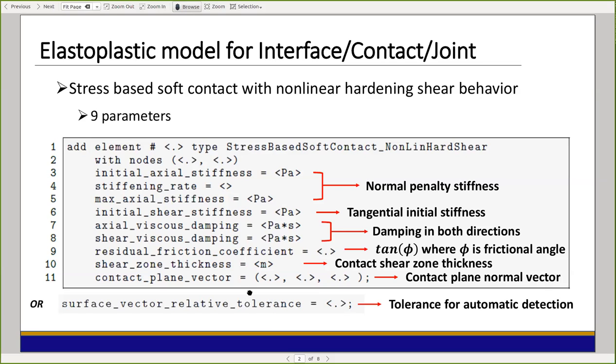Just a comment. This damping that you mentioned is viscous damping. If you think about an interface where something is going to open a gap and close the gap, there will be some suction, some pumping of fluid, in this case air or water. This is the meaning of it in the normal direction. In the shear direction, it's really less than that. But again, these are viscous dampers, essentially dashpots, and they do help stabilize simulations, especially in this axial mode, which is very physical.